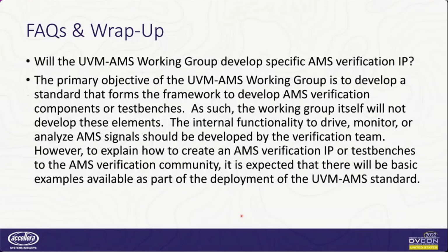Is the UVM AMS working group going to develop specific VIP? The simple answer to that is no, we're not going to develop VIP. The goal is to establish the standards so that third-party vendors can develop VIPs based on the standard that will work just like in UVM, except with the capability of having the proxy to program analog signals and the ability to have an analog resource that can drive analog ports as well.